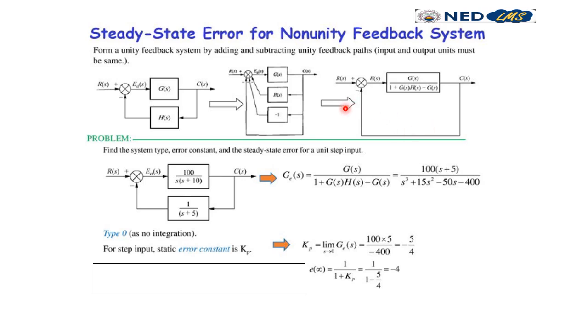So here, because we have simplified this whole block diagram, we have this G(s) upon H(s) minus G(s)H(s). It is actually combined, and this is coming from here, so this is minus G(s). It is actually a long derivation. You can see it in Norman Nise if you want the detailed derivation. Otherwise we just simplify this as G(s) upon 1 plus G(s)H(s) minus G(s). So this is actually the method how we simplify this type of non-unity feedback systems.